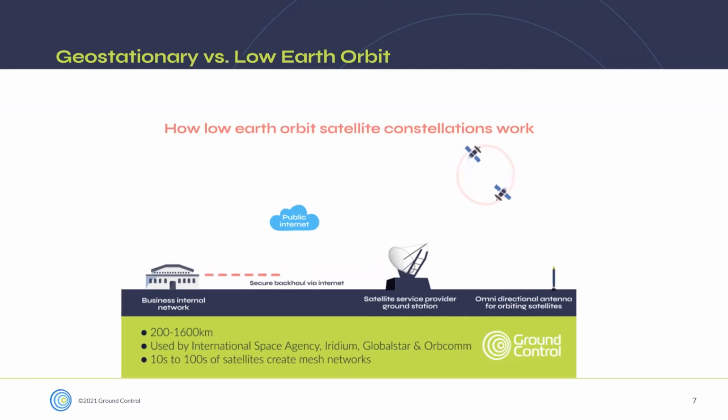So I think the summary of that point is 3 choices. Make sure your terminal is pointed appropriately to the satellite. Use an auto pointing device, of which there are many Inmarsat services available that offer auto pointing, or use a low Earth orbit device that doesn't need to be pointed because it's going to hit one of these rotating satellites by some mechanism. So there's no need to make sure it's pointing in the right direction.